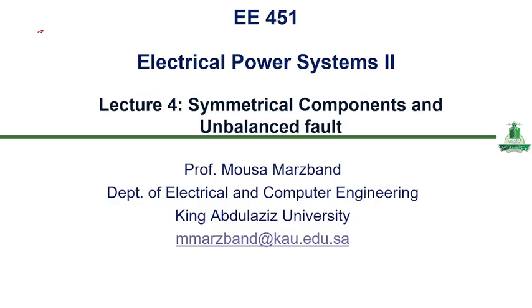The method of symmetrical components provides a powerful and systematic approach by decomposing unbalanced three-phase quantities into three balanced sets: positive, negative, and zero sequences. Throughout this lecture, we will explore how these sequence networks are constructed and interconnected to model different types of faults.